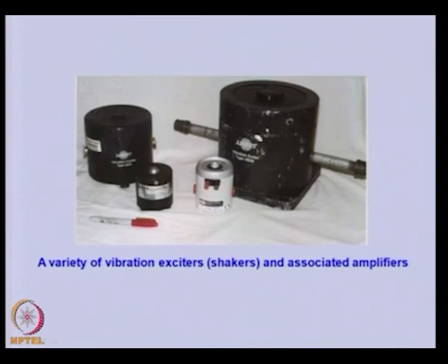With this we can excite the machinery externally, and we can choose either the frequency of excitation or the amplitude, or even what kind of excitation force we want to give, like sinusoidal, two frequency signal, multiple frequency signal or random signal. So, depending upon the application, we can excite, and then measure the corresponding change in the vibration, which can be used to find the condition of the machine.